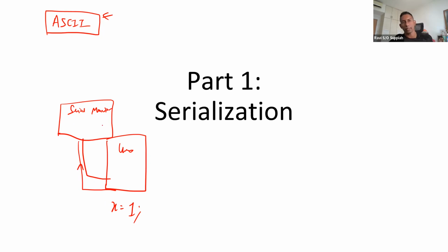It won't print out as 1, because the 1 translates to another character. For numbers, if you look at the table, it starts off with 0x30, all the way to 0x39. These are all the numbers that map from 0 all the way to 9.